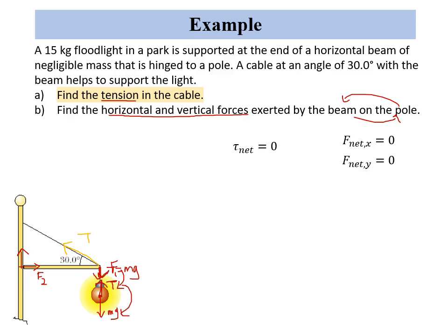You can label them as F2 and F3. Now I'm going to redraw this diagram, but I only want to look at the beam itself, because the other things can be a little confusing, and I'm going to label all of my forces. We always start with the second condition of equilibrium, and to do that, you need to figure out where you want to place your rotational axis.